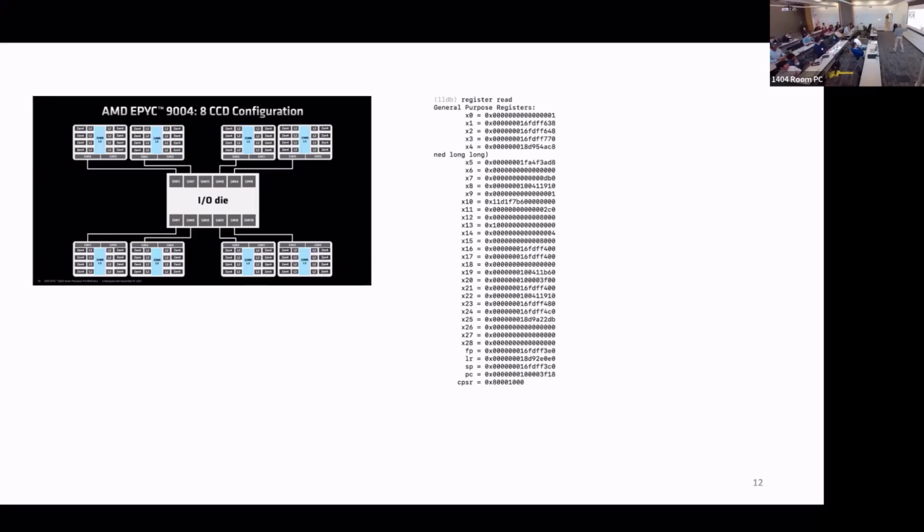And then in response to the comment about what's this, a CPU is a finite state machine: on my laptop, this is ARM, so these are the architected ARM registers that I printed out. This really is what would represent the state of a finite state machine. If you are an operating system and you want to task switch, interrupt one process and start another, this is the thing that you have to save in order to reload the processor's state to start execution again when you come back to that process. You get a program counter that you execute the full instruction from, and so on.